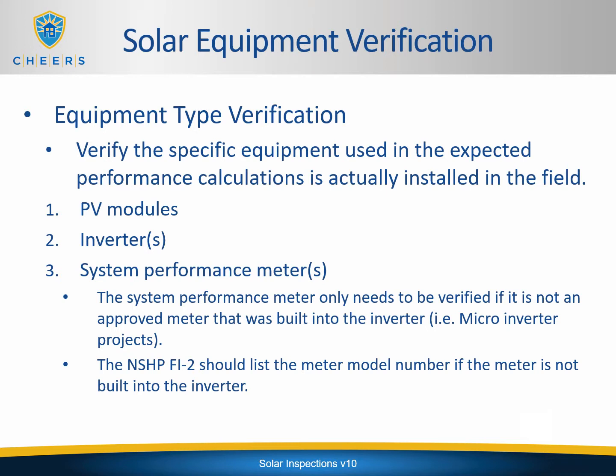Now, the system performance meter will only need to be verified if it is not an approved meter that was built into the inverter, so it would be a separate meter. Commonly, what you will find is that the inverter has an integrated performance meter, therefore that performance meter does not need to be verified because it is part of the inverter. The NSHP FI2 should list the meter model number if the meter is not built into the inverter.